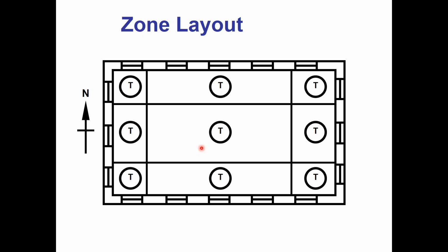He never sees the sun unless it's the top floor of the building and he's got a bunch of skylights or something. But other than that, he never sees the sun. So he never has that effect on him whatsoever, and he never has any thermal heat loss or gain through the walls. So he's going to be unique from all the perimeters. So 9 zones is what I would need to do.